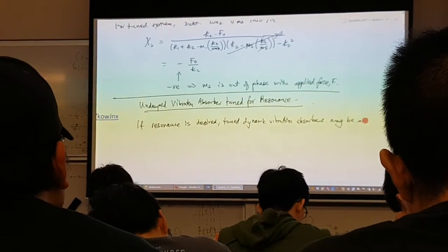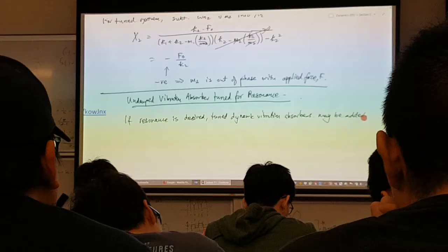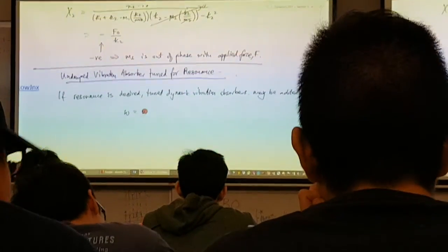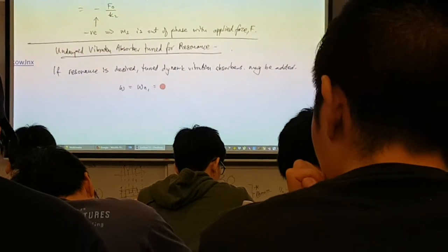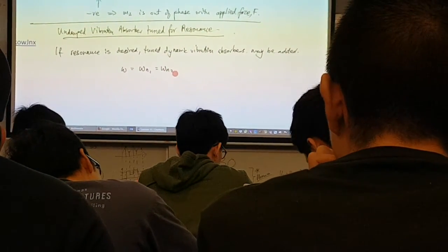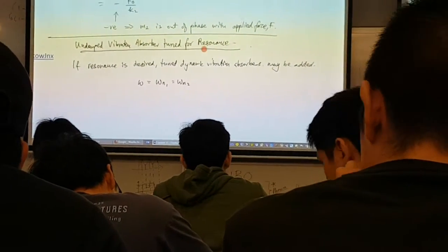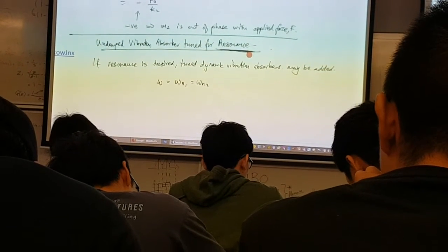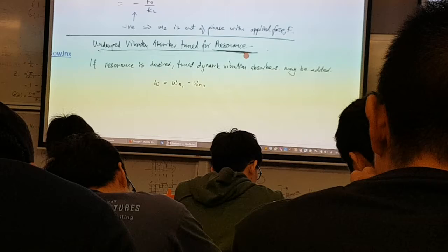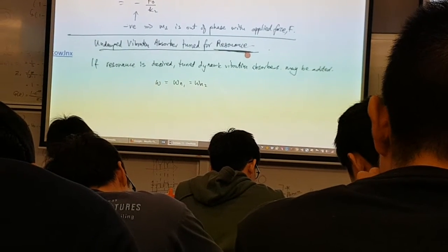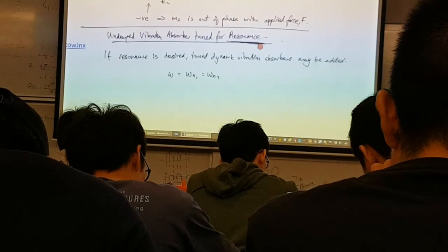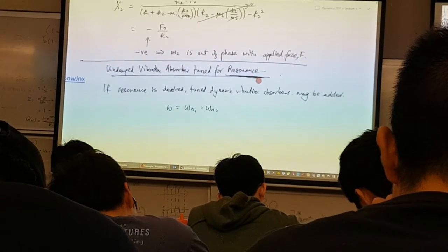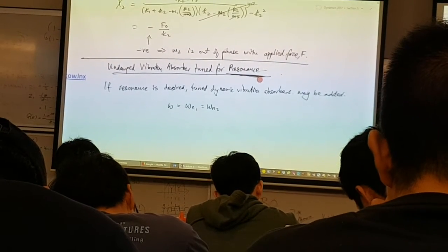What that means is that your omega equals omega n1 equals omega n2. We're interested for the entire structure to resonate. So it's different from the other case where, for the machine, we wanted to have a zero amplitude and then transfer the energy to the mass that we added on top.